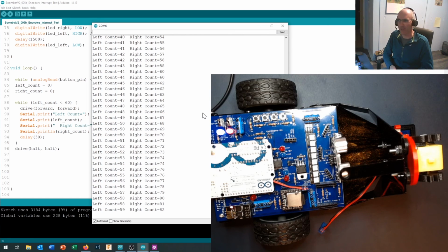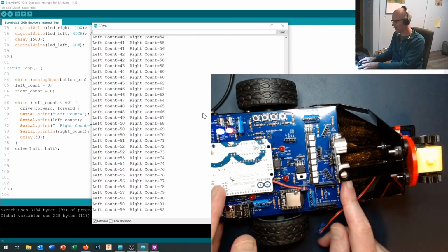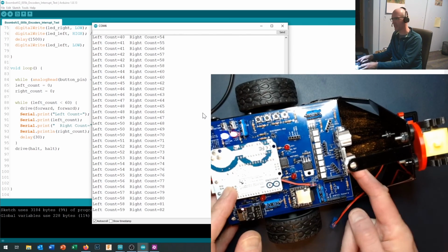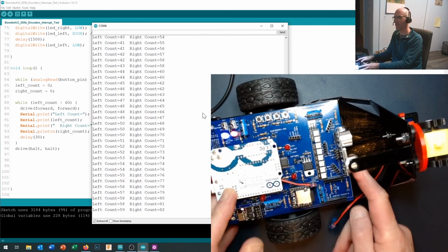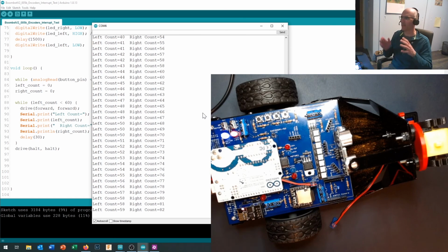This is a little trickier than some of the things that you've done already. You do have to get it set up and get it into position, just like so, so that you're reading those encoders properly. Using your DP scope for that can really help you out. Once you're done, put it on the floor, drive 1 meter, take it back, drive 1 meter forward, drive 1 meter back, and you will have dead reckoning position control of your Boombot.